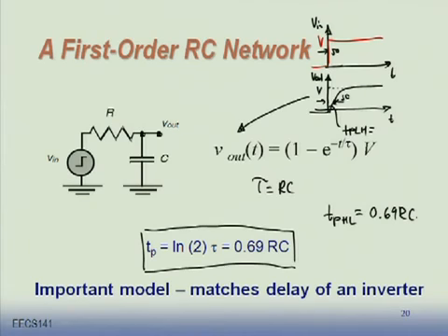Output of this waveform. So you asked me what is V out. V out was the output. You'll find out in just 15 minutes that this pretty well approximates how an inverter responds to a waveform. Why do we like this? Because it approximates well the delay not only of an inverter, but of a logic gate in CMOS.